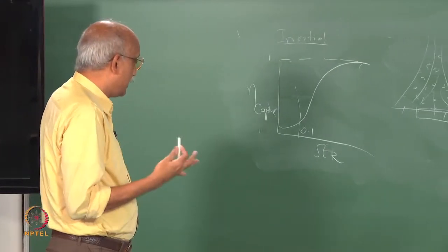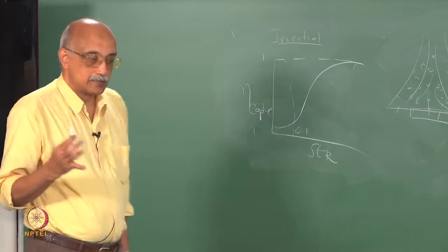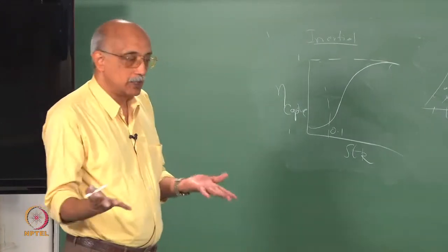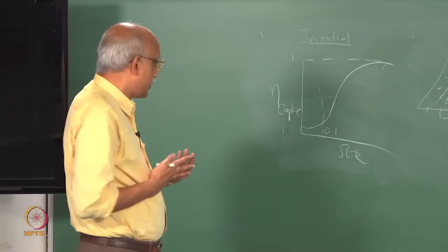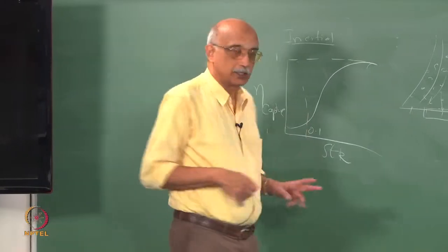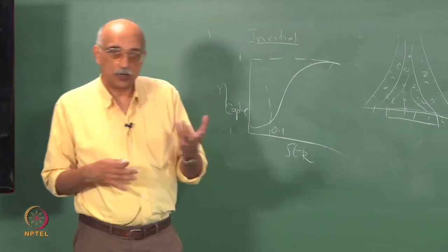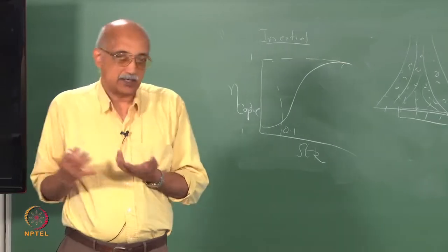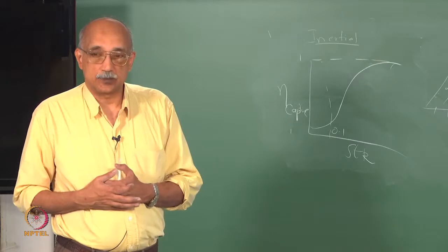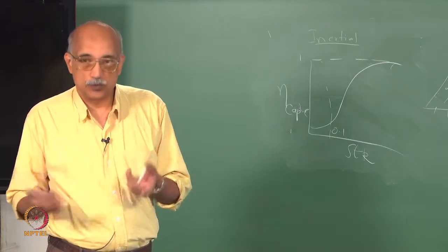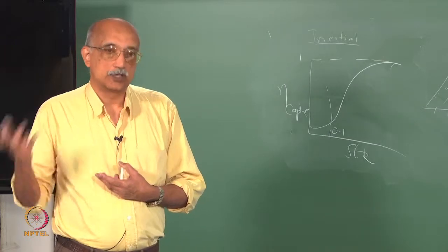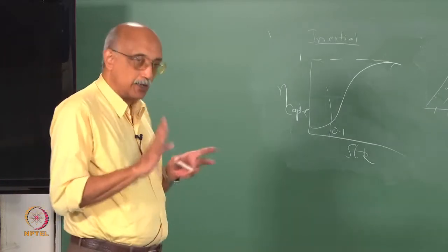So, you could say, for example, that I have a process in which I do not want particles to deposit on my surface. If I want to minimize deposition by inertial impaction, then you would want to operate at a low Stokes number, which corresponds to a low particle diameter. But then what is the negative consequence of that? There are other transport mechanisms that come into play. What we discussed yesterday, diffusion and electrostatic effects, actually become stronger when you reduce size. So, you have to be careful.